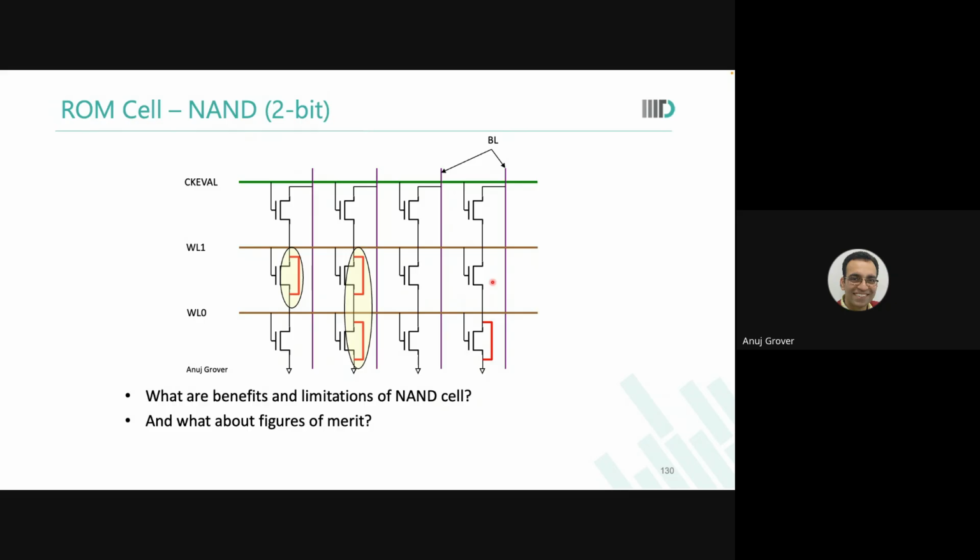There, you don't even need to do this for programming, whereas here you have to put a contact for programming. We're only talking about DRC spacing, but in Flash, you program in a completely different way. So you will see that the benefit or advantage of using a NAND flash or a NAND structure in the non-volatile cell will be very, very prominently visible to you. Is that okay?